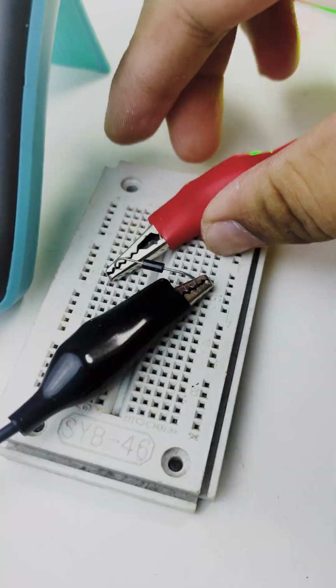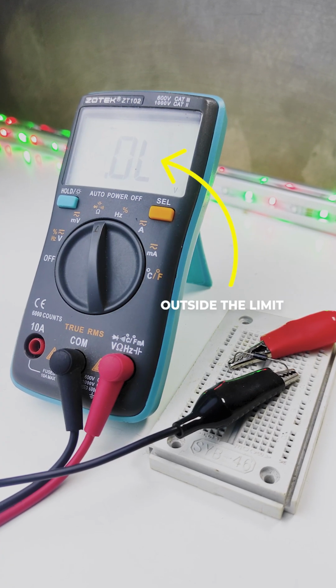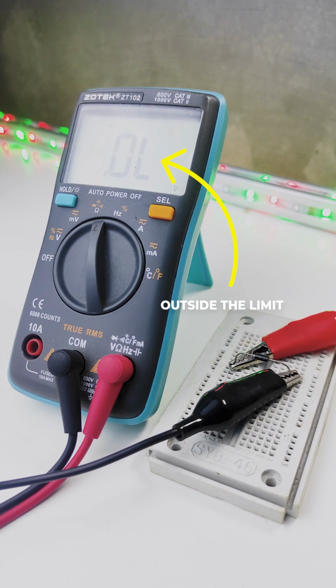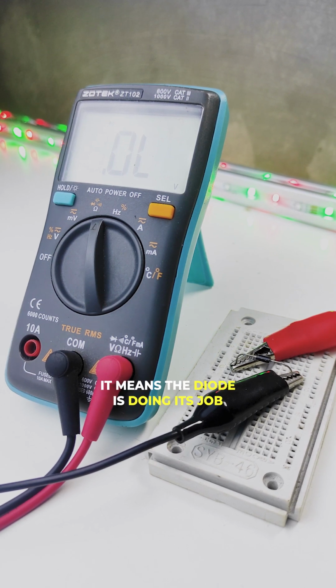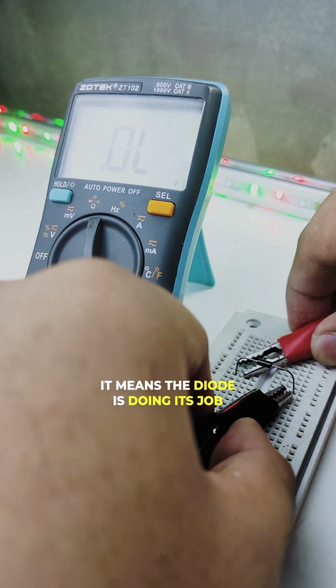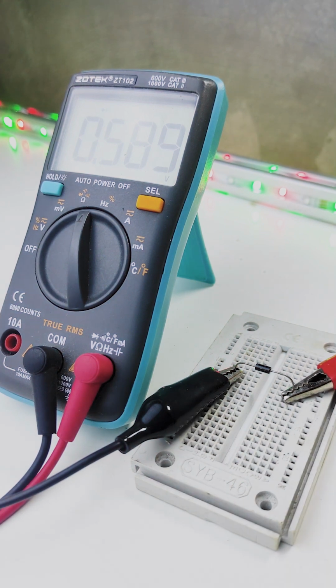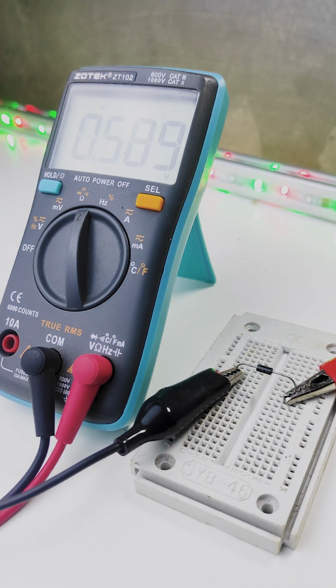Now, if we flip the diode, we should get OL, which means outside the limit, and that tells us it's not able to make a measurement. And that is also a good thing because it means it can block the circuit. So the diode is doing its job. If we get a reading in both configurations, then it means that the component is faulty and shouldn't be used.